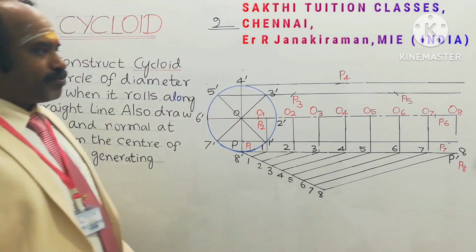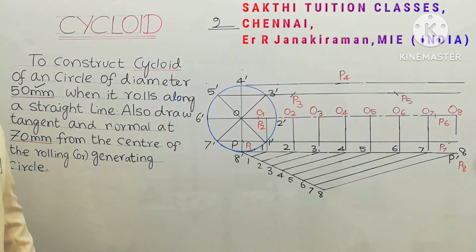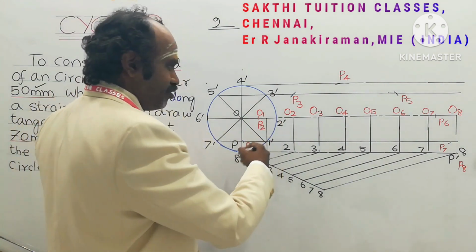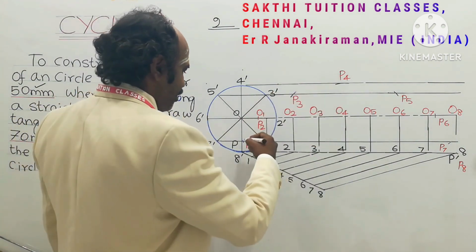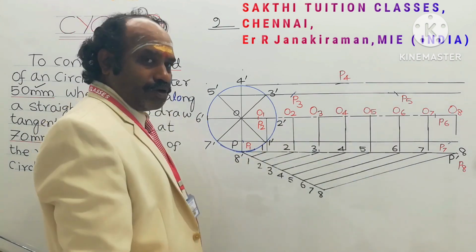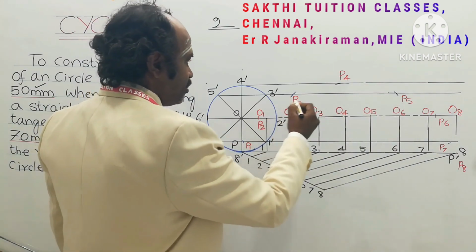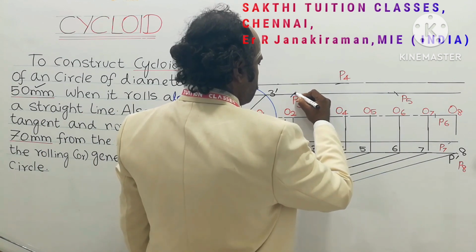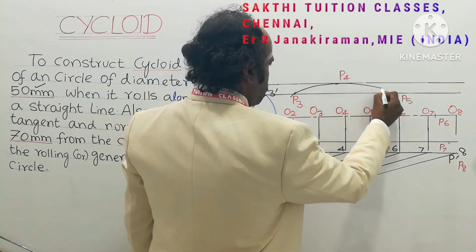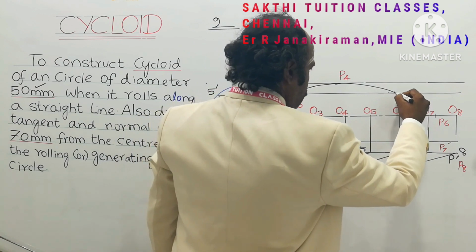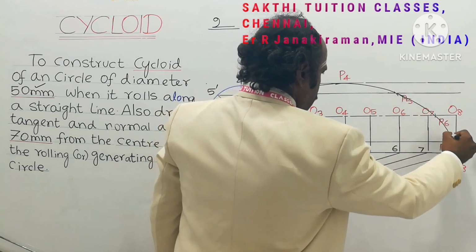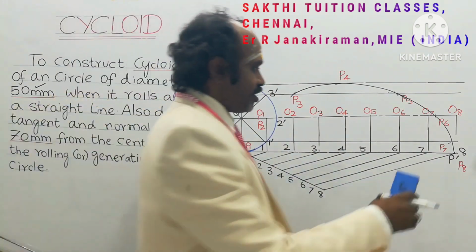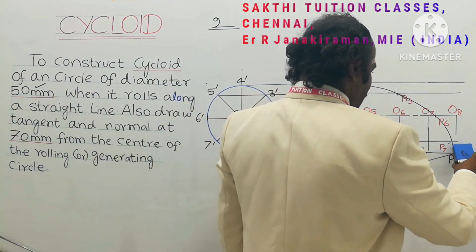Understand? So draw a smooth curve passing through these obtained points starting from the letter P. First you draw it with a lighter line, then you can make it dark, but don't paint the curve and don't use the scale for this. So let me join the smaller points. Suppose if it goes wrong, you can correct it just by erasing that part.